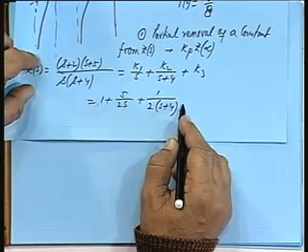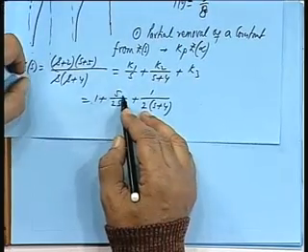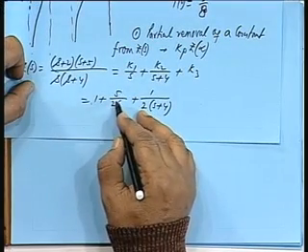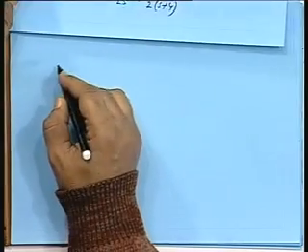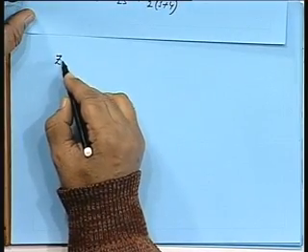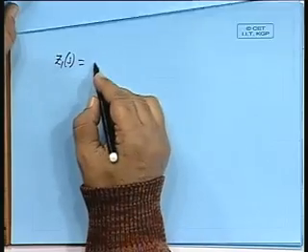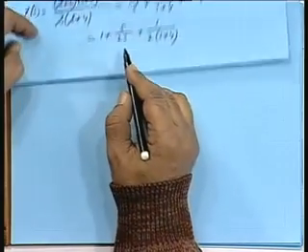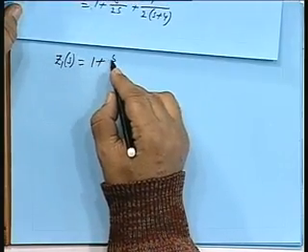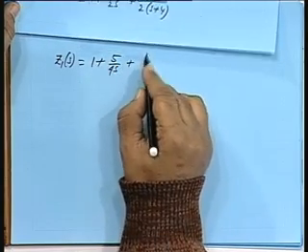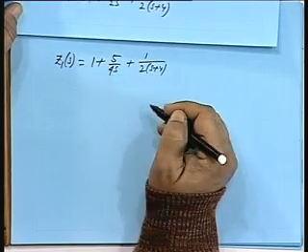If instead you remove, okay, we had, once again I will start from the same function, Z(s) is equal to 1 plus 5 by 2s plus 1 by 2 into (s plus 4). Suppose we weaken this one partly, this pole, what happens? So, Z1(s) will be 1 plus, suppose we remove 50% of it, so 5 by 4s we retain, plus 1 by 2 into (s plus 4).